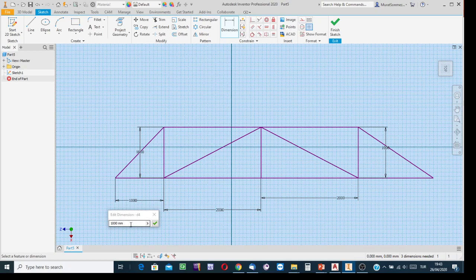Of course, we select the lengths of the cells regarding the strength of the members, the maximum deflection of the bridge or truss, and of course the span of the truss. If the bridge across the river is, for instance, a span of 10 meters, then the total length should be minimum 10 meters, from abutment to abutment, one side to the other side. So not arbitrary, consider the span of the river, or sea, or whatever it is. If it is a roof structure, then consider the maximum size of the roof, then accordingly decide how many cells you need to use. Okay, and it is the other issue.